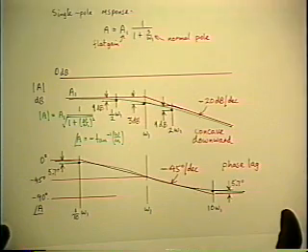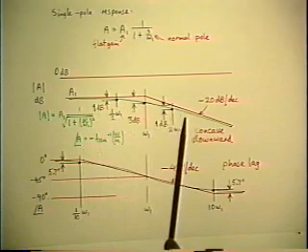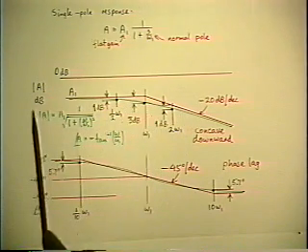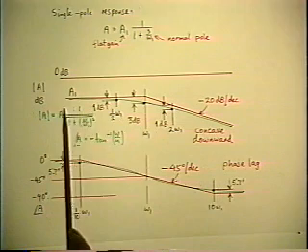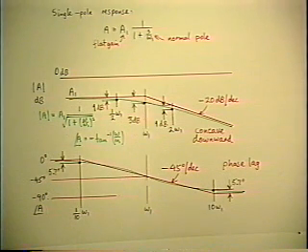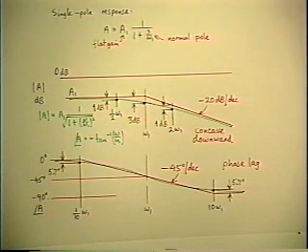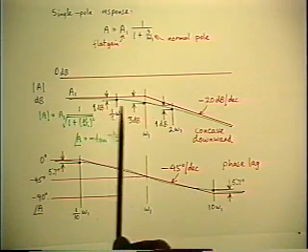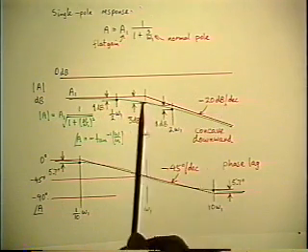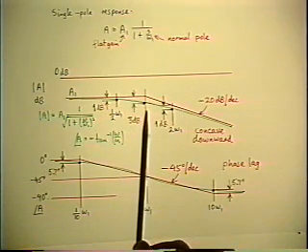Well, everyone knows that that's the 3 dB down point, and really all you have to remember about the asymptotes for a single pole function are that you have the sharp corner of the asymptotes and the actual curve is 3 dB down at that point. There's a couple of other points that are useful to know about also, because the only thing that you don't know by using only the 3 dB down point is that you don't know what is the frequency scale involved. You don't know how far this gradual curve is extending on either side of the actual corner.